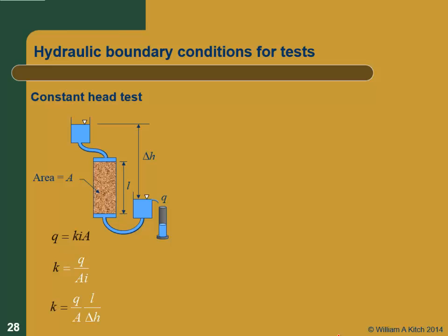And generally, there's a good discussion of this in your lab. There's some evidence that at very, very low hydraulic gradients for clay soils they may deviate from Darcy's equation, but there's also later published data that indicates that might just be an artifact of the test. So for all practical purposes, I think we find that Darcy's equation works fine for fine-grained soils and coarse-grained soils. It doesn't seem to be a problem.